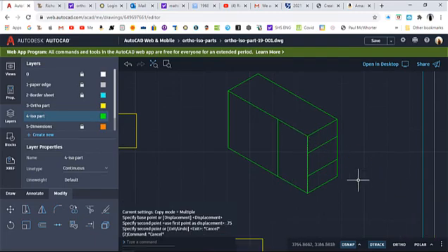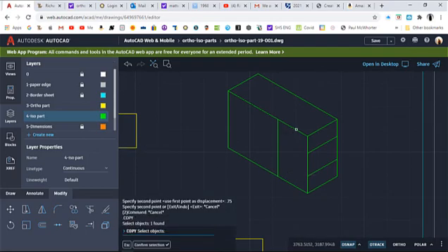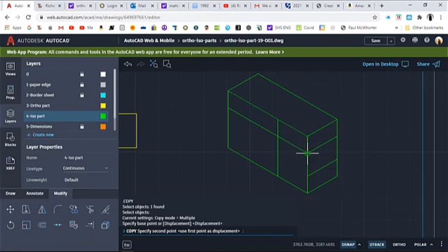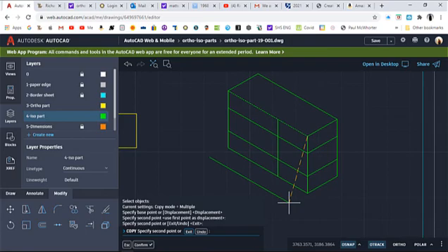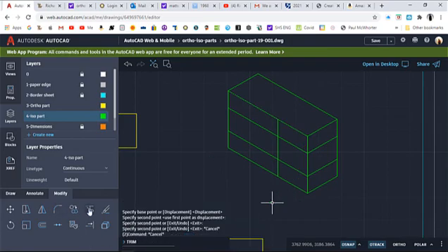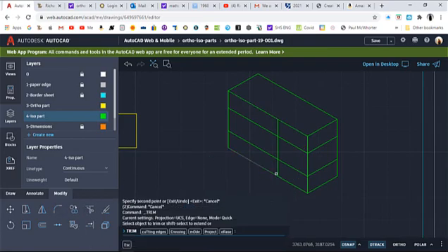That looks good. And why not go ahead, hit spacebar again, select that object there, enter, grab this point here, and just snap to that vertice. And then we'll come down here, snap to that vertice as well. Hit escape. Let's go find our friend, the trim command, and we'll trim him. There, and we'll trim this one here and this one here.